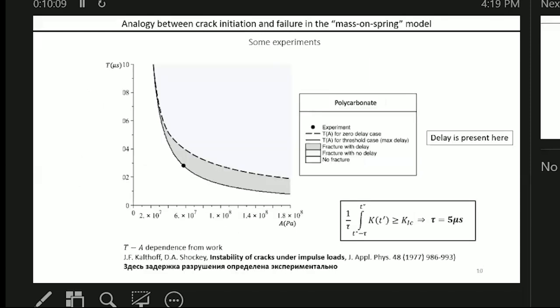But the same group headed by Kazarinov actually did experiments where they saw the fracture delay. They confirmed that the crack can start when the stress intensity derivative over time is negative, so when the stress intensity already drops. So we used this information and built the same curves using this one point, showing that it's the point of the fracture delay, and we constructed again these two curves.